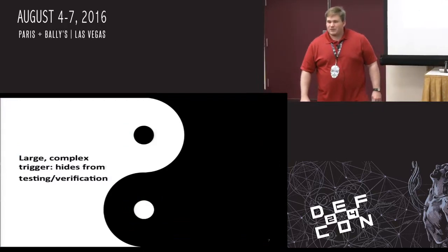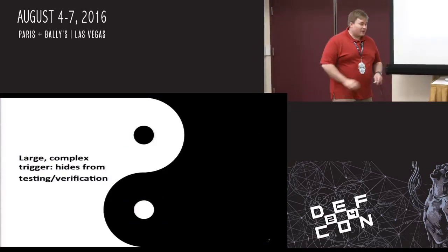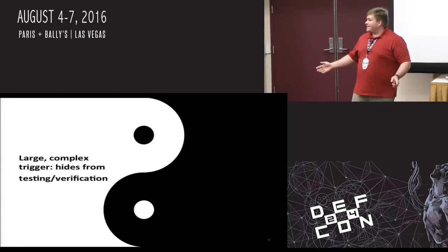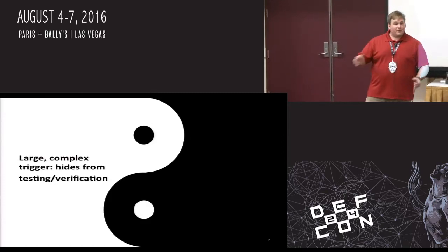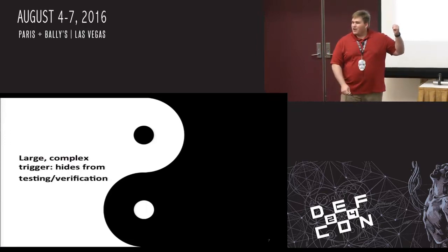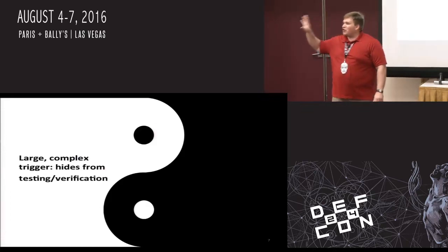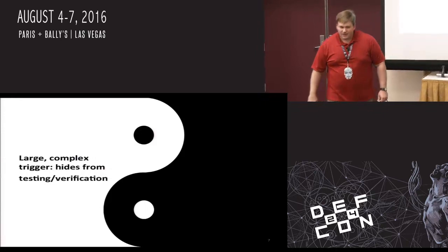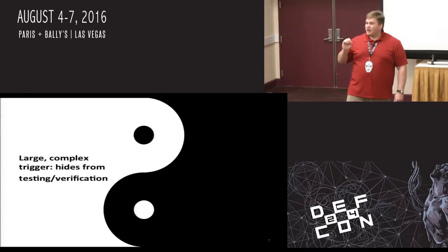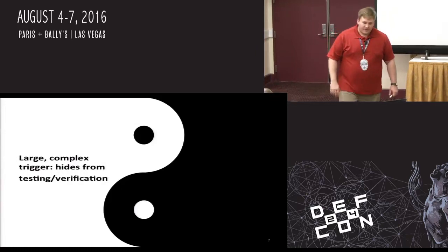In the academic space, we've seen two types of attacks, and they're all based upon how I am going to prevent my attack from being noticed. One of them says, listen, I know you're going to run some sort of functional verification, some testing, and I don't want my attack to influence behavior, so I need to hide it. How do you hide your attack? You use this thing called a trigger, which is basically a very complex state machine to nest your attack in the dark recesses of the state space of the processor. Imagine a bunch of if statements in software. Something like that makes the condition to trigger the attack very unlikely to be accidentally or even intentionally bumped into.